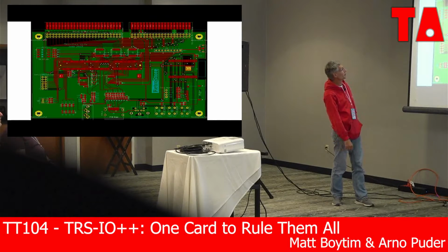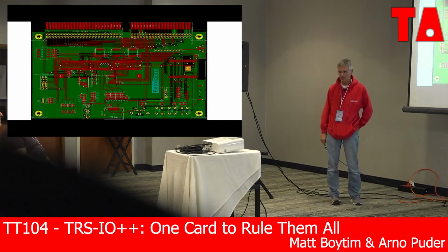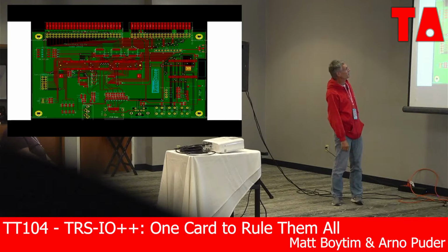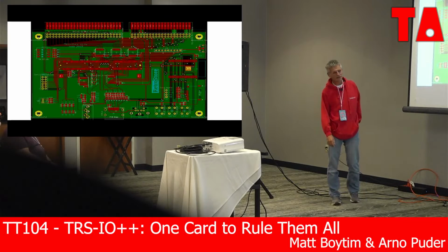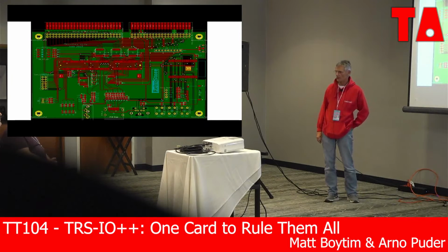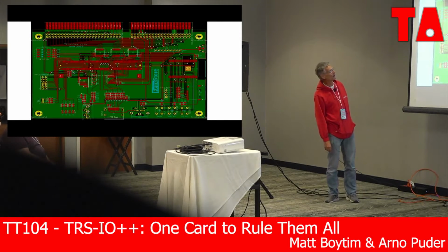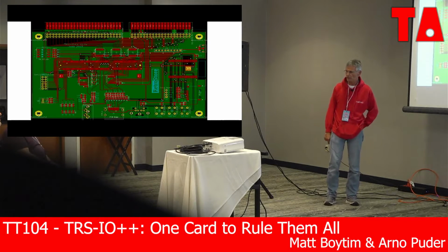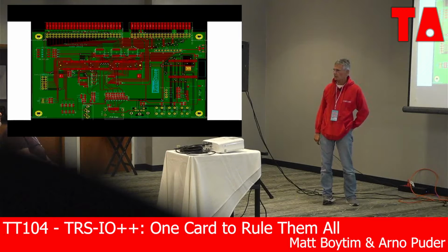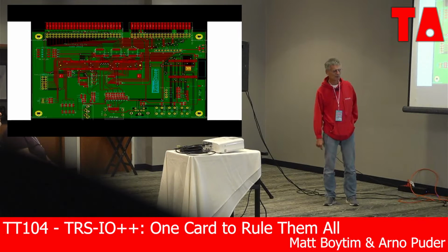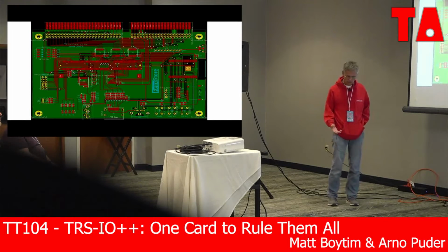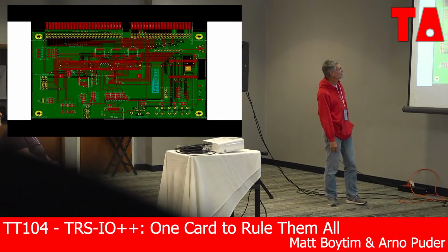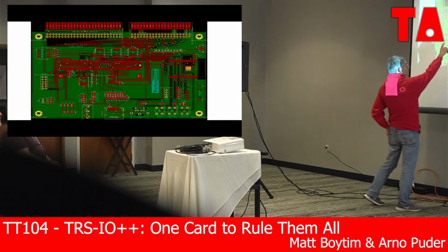One of the interesting things about it is the arrangement of the Model 3 interface is much more regular. You can see the lines very uniform. On the Model 1 side, you can see that they're just all scattered. There's really no particular organization to it. Very poor grounding. Quite a bit of the work that I did was trying to improve the grounding on the Model 1 connector, because the biggest problem, in my opinion, with the real Model 1 is noise.